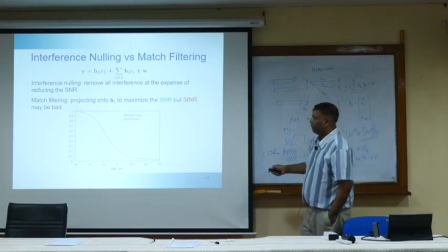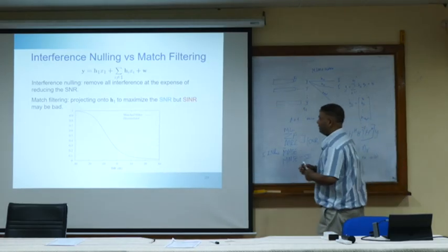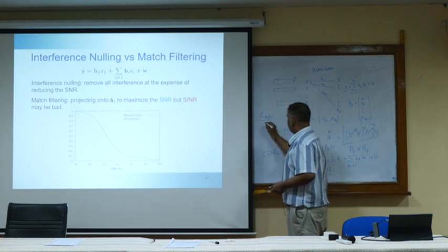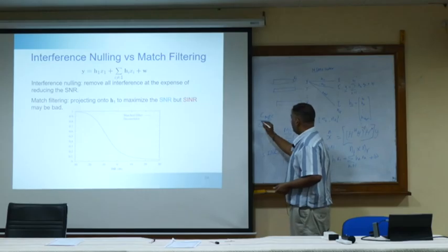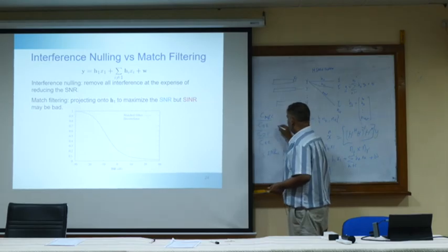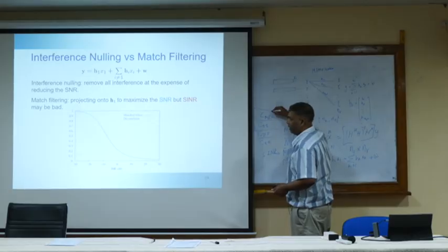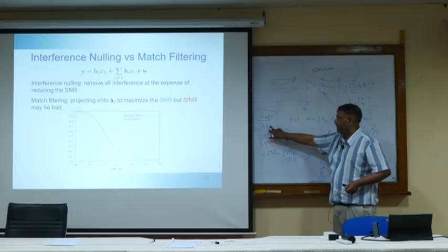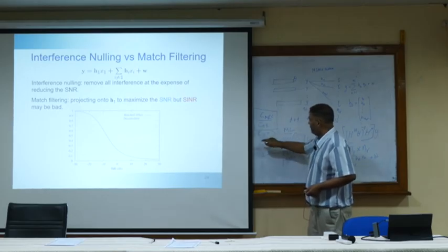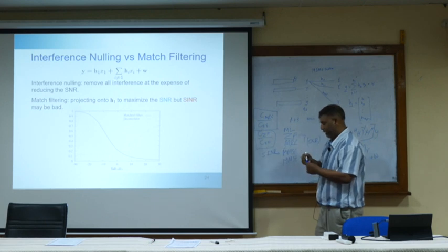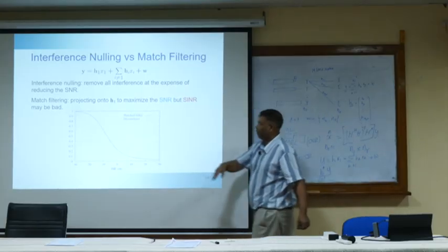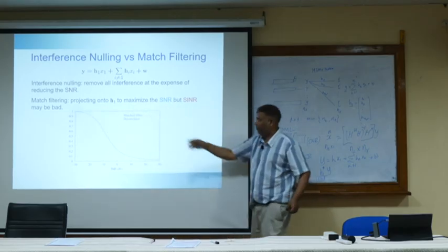Okay, so here is the performance. The y-axis is the capacity of the maximum ratio combining divided by the capacity of the 8 transmit and 8 receive antenna case, and also the capacity of the zero forcing divided by the capacity of 8 by 8. So there are two plots. The solid line is for the maximum ratio combining divided by C 8x8, and the dotted line is the capacity of the zero forcing divided by C 8x8. If these achieved capacity, this ratio would be 1. That maximum is 1, because it's a normalized capacity on the y-axis.